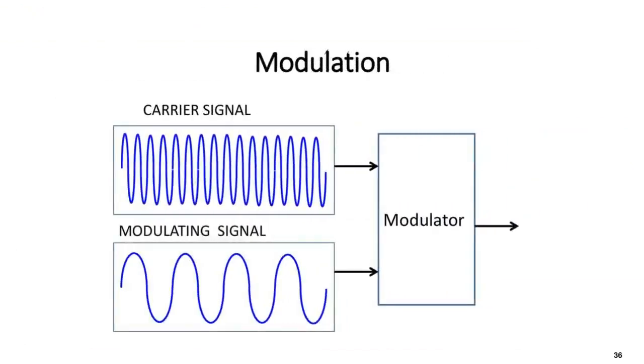All right, so what's modulation? We talk about pulse width modulation. What does all that mean? Well, we take a carrier signal and some kind of modulating signal. Now in radio transmissions, the carrier is the frequency that we tune in on our dial, and the music or voice or whatever we're transmitting is the modulating signal. That goes into a modulator and in the course of a radio, then out to a transmitter.